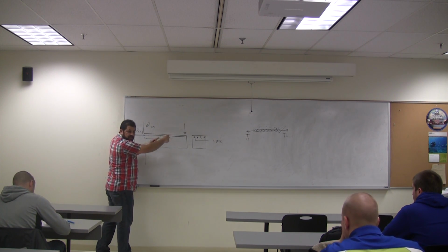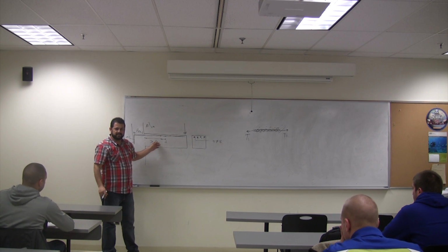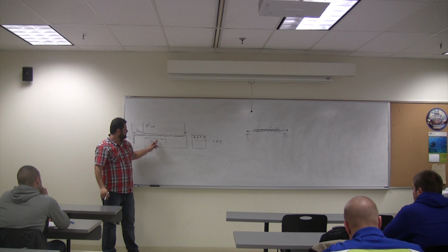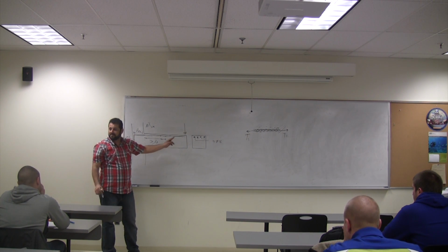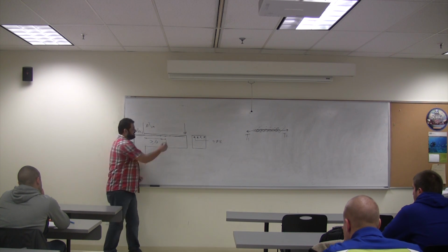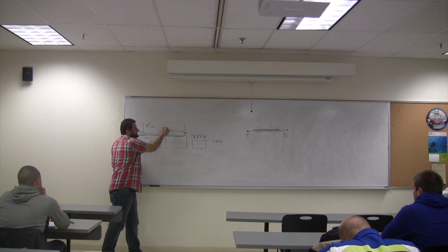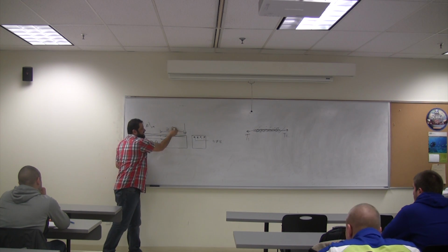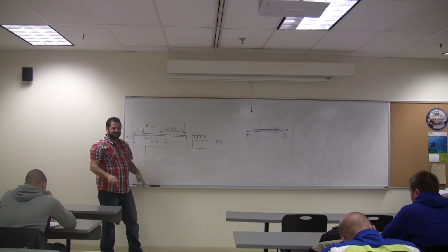Is there anything else that needs to be greater than ld? How about the remaining 2 bars? From here to the theoretical cutoff points must be greater than ld, so that now those 2 will develop a fy for you here.